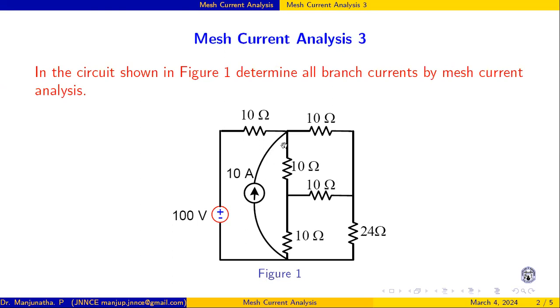But we can't do anything here because look at this. This 10 ampere is in parallel with this. You can say straightly, in this way you can draw here. It looks like something like this between this 10 and 10. Also it is between these two points. So what can I do? Can I change this voltage source so that I can do some simplification?